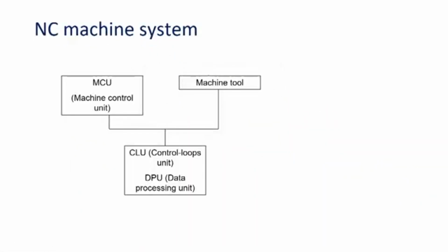It is generating the movement of the work parts, controlling the movements of the tool in relation to the work parts, and these are to be meticulously executed as per the instructions given by the user. So, data has to be read, the data has to be decoded, and then the control loop has to be executed in a proper way to control the machine tool.